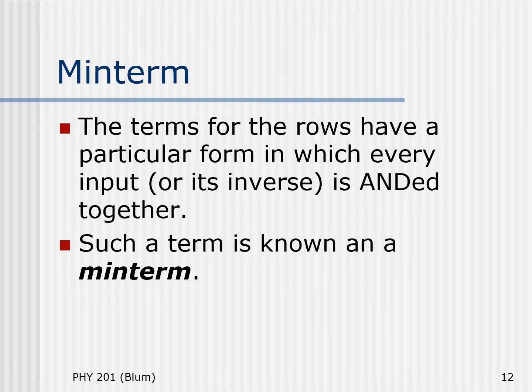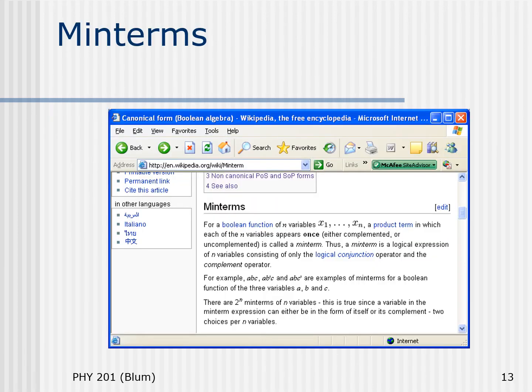So another term for sum of products is minterm. It's important that we don't do any simplifying and that each term involves all of the inputs. Then that is specifically a minterm expression. If we have the sum of products, it's actually the individual products that are minterms, but we'll still use this term minterm for this approach.